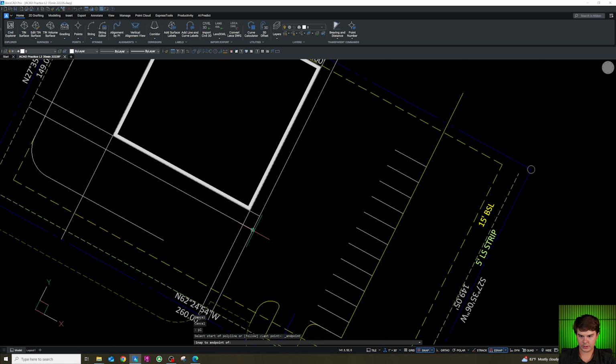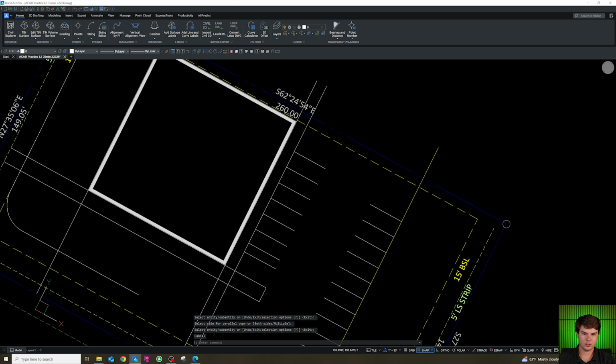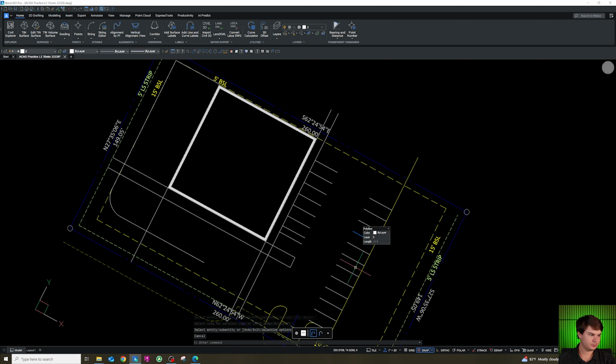Here we're going to come out 19 feet for parking. Looks like we have an 8-foot island. And then we have a van space, 5 feet for hatch, 8 foot for ADA parking, and 9 feet for the rest of the spots, so 1 space, 2, 4, 5. So it goes there.